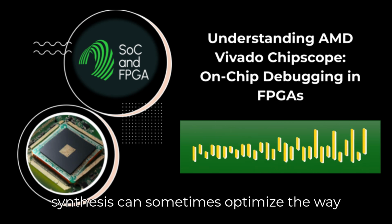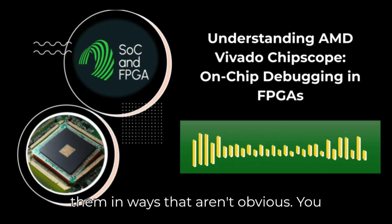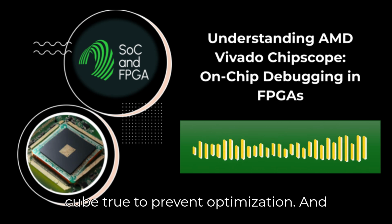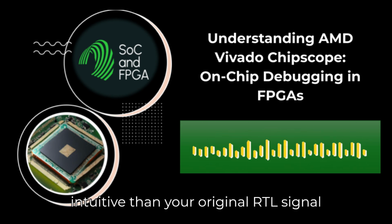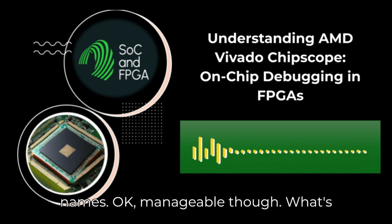Well, synthesis can sometimes optimize away signals you wanted to probe or rename them in ways that aren't obvious. You might need to use attributes like keep true to prevent optimization. And sometimes working with those post-synthesis net names can be a bit less intuitive than your original RTL signal names. Okay, manageable though. What's method 3?